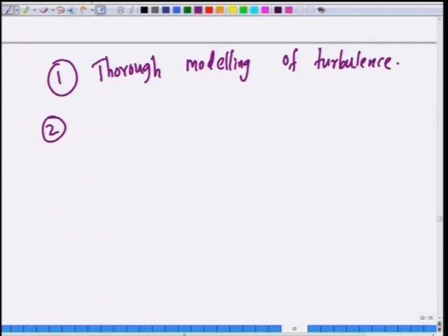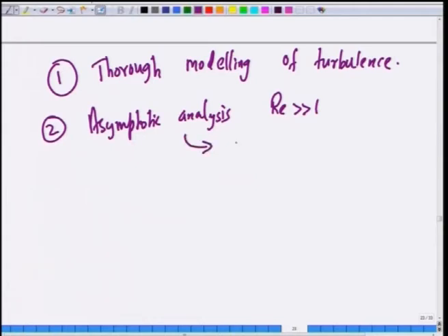And we didn't do the boundary layer analysis in a rigorous manner. We did the simplified integral momentum approach, but it is possible to use what is called asymptotic analysis by exploiting the fact that the Reynolds number is a large parameter in boundary layer flow, and then we can derive the boundary layer velocity profile exactly, in the limit of high Reynolds numbers. By throwing away terms that are systematically small at high Reynolds numbers, it is possible to derive the velocity profile in the boundary layer.